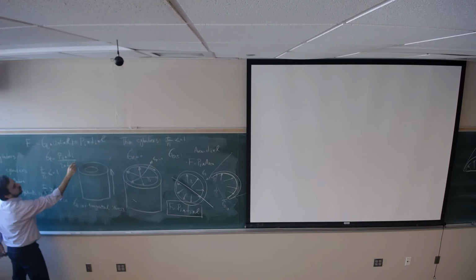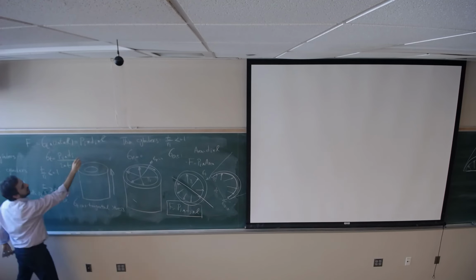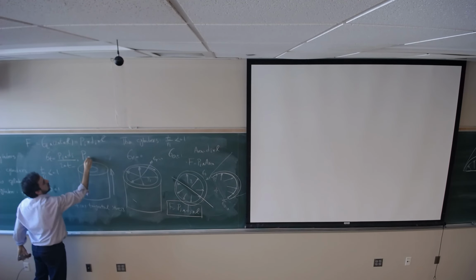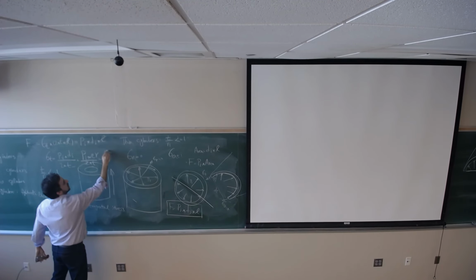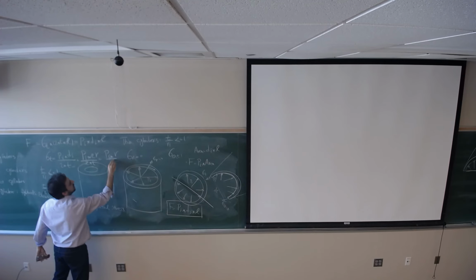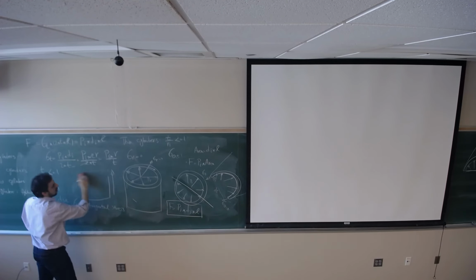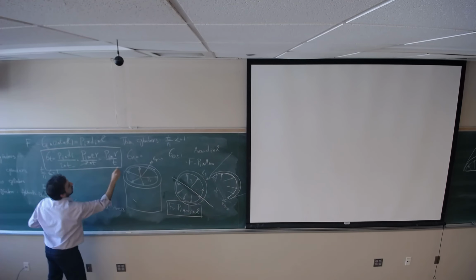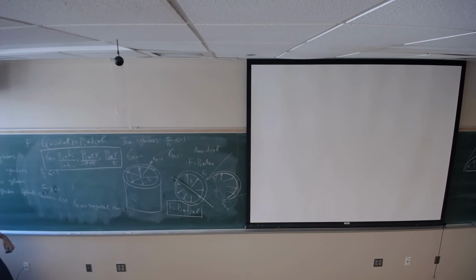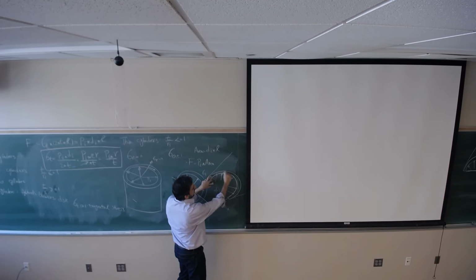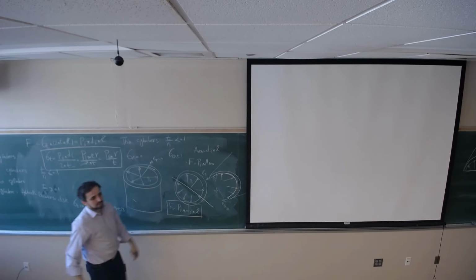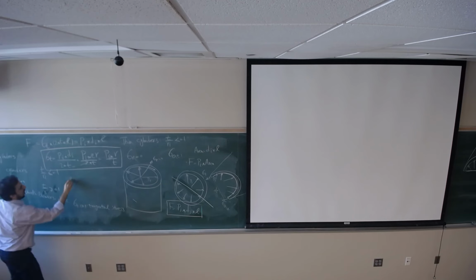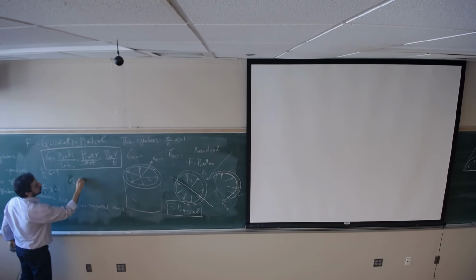The Di is 2 times r, so 2 times r divided by 2 times t. It's going to be Pi times r divided by t. Should we specify that as RI or just R? Pardon? Should we use RI or just R? I mean, since it's a thin wall, RI and RO would be the same, basically. RI equals RO.